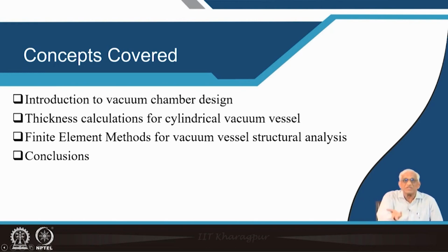Similarly, the surface finish inside is going to be very important. The apparent area that we see with our naked eye on inside surfaces which are actually exposed to vacuum is much less compared to the actual area, because unless you polish it very nicely, just 2πRH is not the area of a cylindrical shell. It may be much more, because there is some 10 micron bad finish.